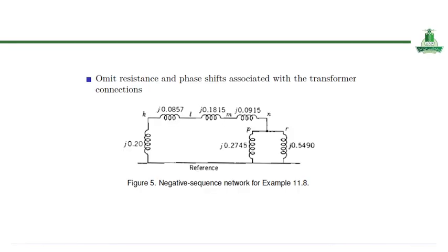So the diagram retains the same topology as the original system with buses labeled from K through to N, and includes the series reactances of transmission lines as well as the machine reactances. All of the reactances have been included here in this diagram. Unlike the positive sequence network, there are no internal voltage sources shown, since in the negative sequence network, sources are typically set to 0.